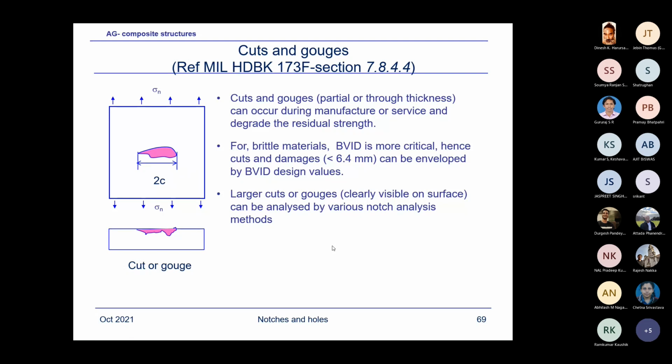If it's only, say, one layer out of 8 layers which is damaged, you may consider, okay, what I can do effectively, if I have to determine the residual strength for one scratch or 1 ply or 2 plies deep only, you may do the analysis using that, by considering 1 or 2 plies ineffective. They don't carry any load.